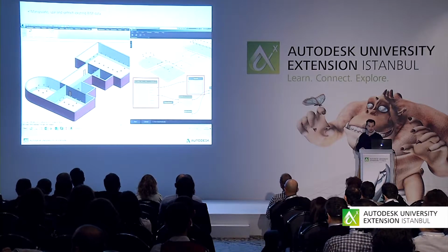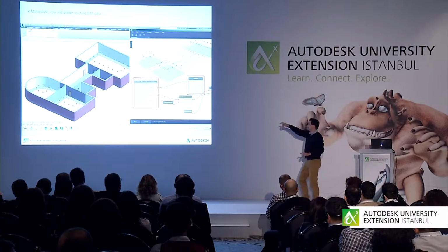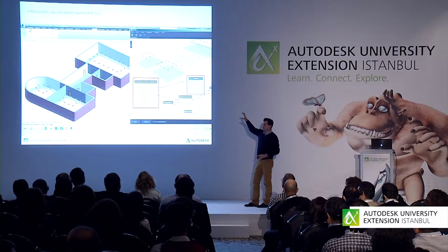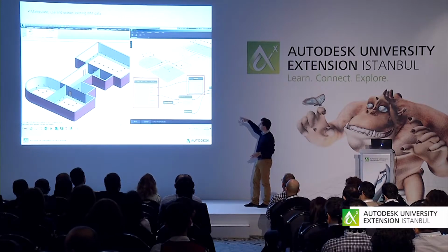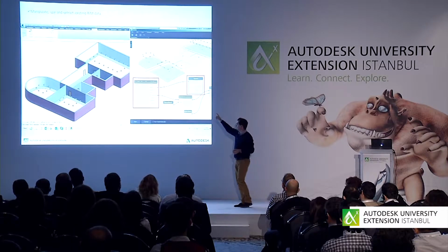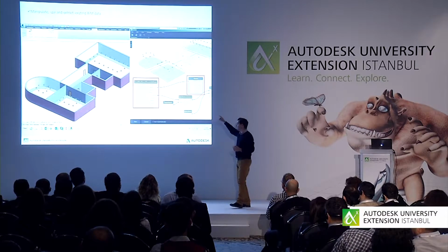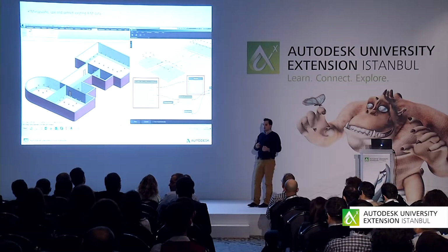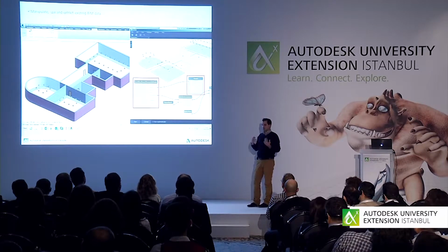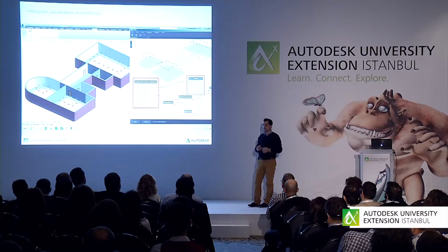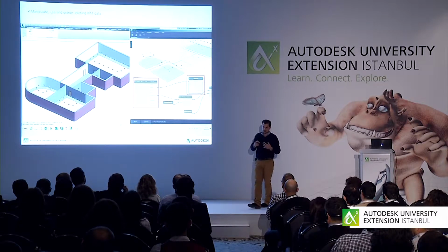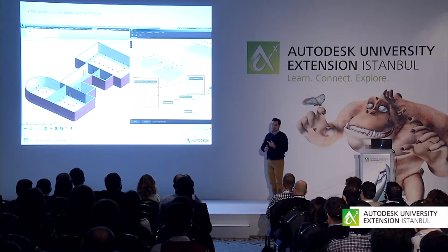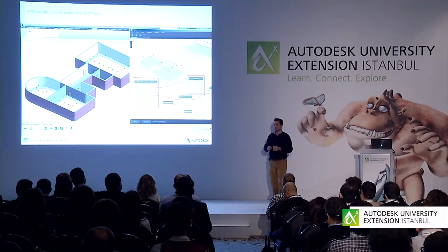Okay, and by the way, here in this example you'll see that by extracting the outlines of rooms, you can control the type of floor, but also with Dynamo you can control that every room has an adequate number of lighting fixtures or adequate number of diffusers.